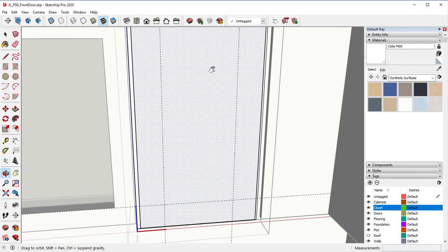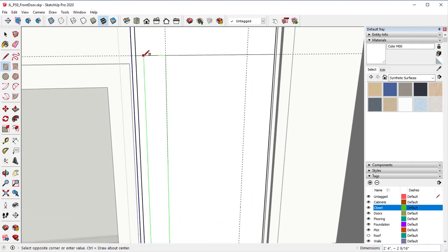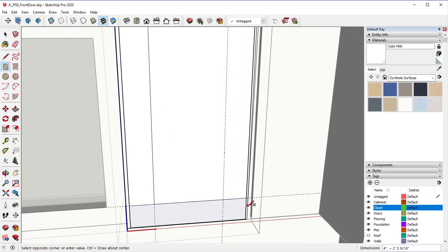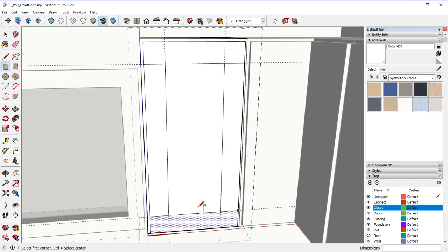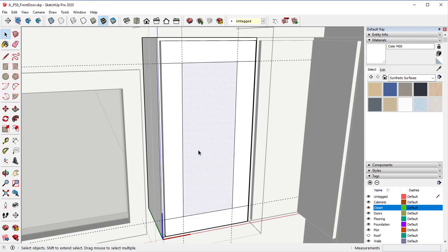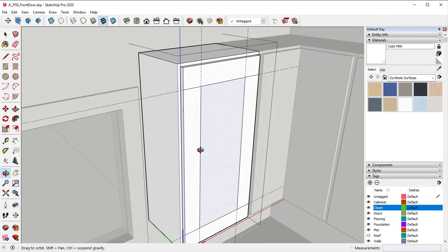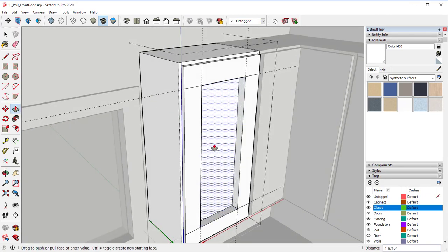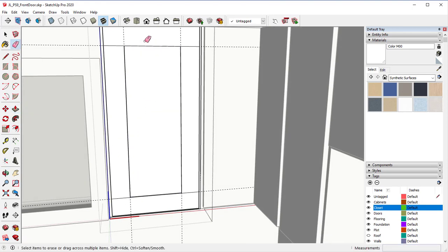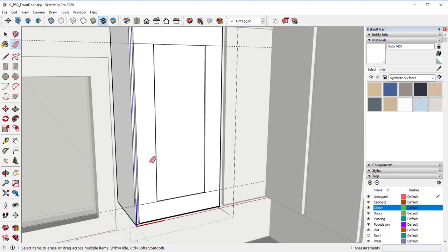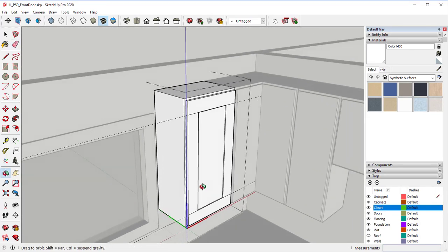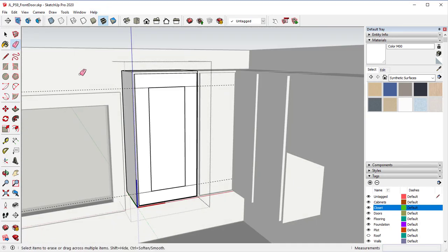So once I have all of that, I'm going to do the top and bottom, then we'll do the sides. Now that we have that, hit spacebar, select the center, as it sometimes doesn't select over when you're using the push-pull tool. Click on the center, push it inwards, type in 0.25, hit enter, and now we can erase those guides. And that's really all that we're going to do with this. That's going to create the look that we want.